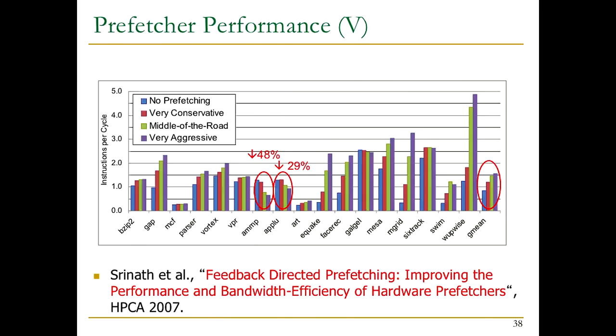Because it actually helps a lot of programs. If you look over here, being aggressive helps a lot of programs because memory latencies are so high, you want to cover it. And some of these workloads actually have very nice predictable patterns. So mgrid, for example, does multi-grid simulation, and you can imagine it works on these matrices, and it is very predictable. But some of the other ones, for example this one, I think this modeled the atom somehow. I don't remember now. But it definitely had an atom data structure. But basically, this one has very large strides that the prefetcher is not able to capture.